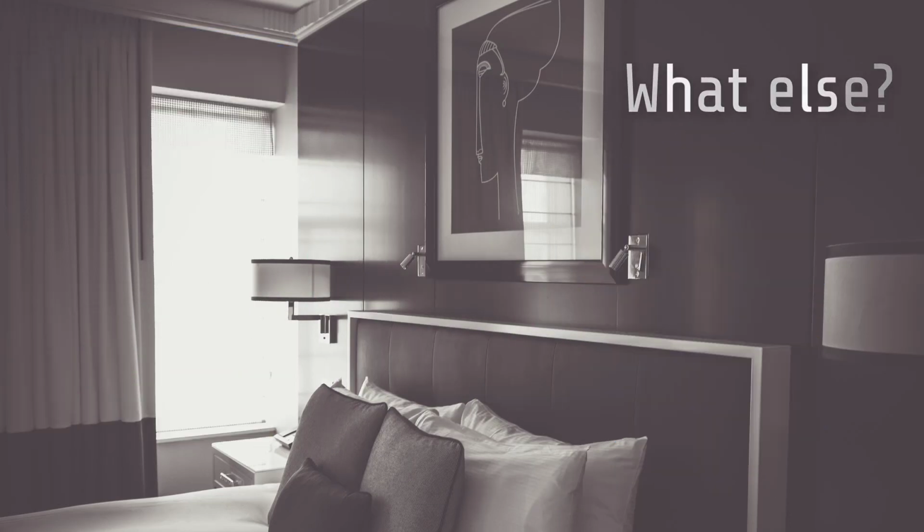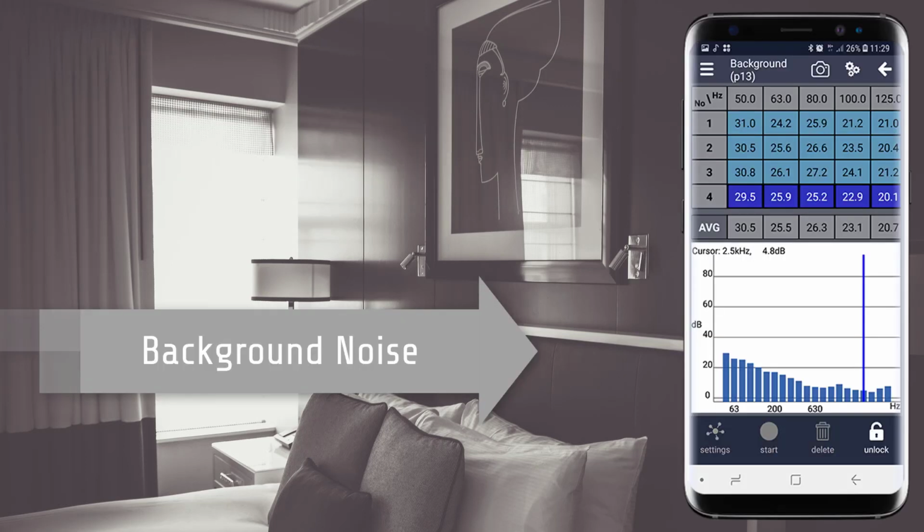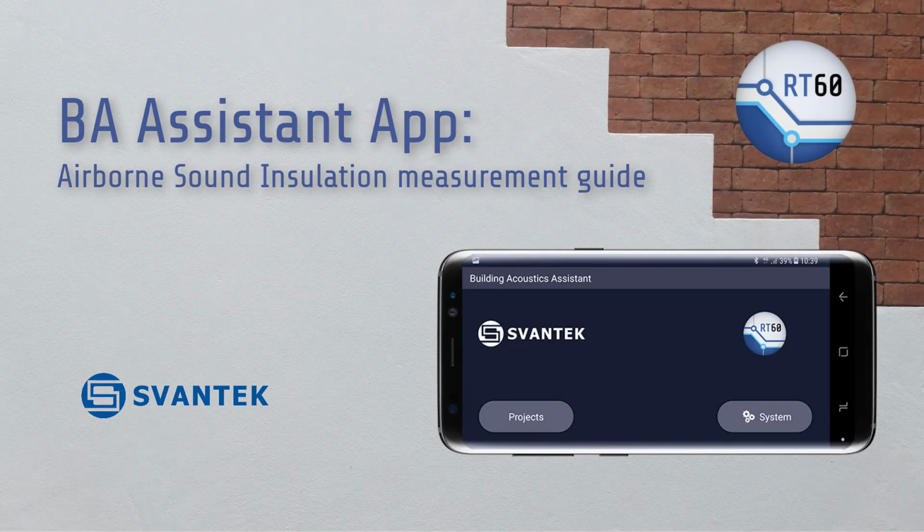Reverberation time, RT60, is the time it takes for the sound pressure level to fall by 60 decibels after the sound has been turned off. Background noise is the noise at a given location and time, measured in the absence of any alleged noise nuisance sources. Similar to RT60, background noise is also taken into account in sound insulation measurements.